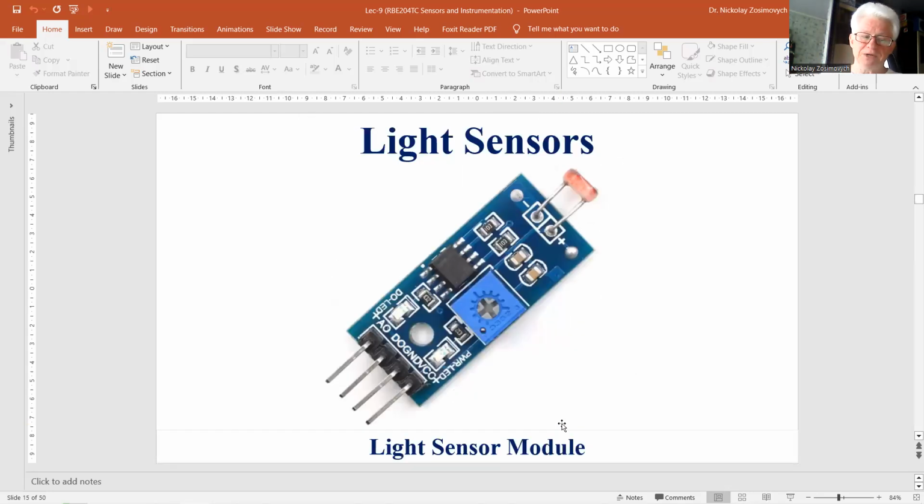Commonly used optical sensors and their general characteristics: photoresistor, small, cheap, sensitive to visible and infrared light, red light, no direction sensitivity, slow, large response time, and a resistive sensor. Photodiode, small, cheap, sensitive to visible and infrared light, moderate directional sensitivity, fast response time, and also available as quadrant detector, 4 diodes in one case.